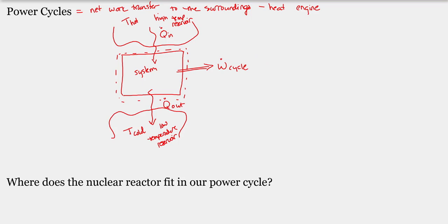So we burn the natural gas. That provides us with heat. We use that heat to heat water, and then that water goes from a liquid phase to a vapor phase. And that vapor phase has a lot of energy, internal energy, associated with it. We saw that when we looked at our turbomachinery analysis, and specifically steam turbines. So I take my liquid water, I heat it with the heat from the combustion of fossil fuels. That takes it to a high temperature steam or high temperature vapor. That high energy vapor is then expanded through a turbine. The turbine spins a shaft, and out of that shaft we connect it to generators, and then we connect it to the power lines, and that gets us power out into society.